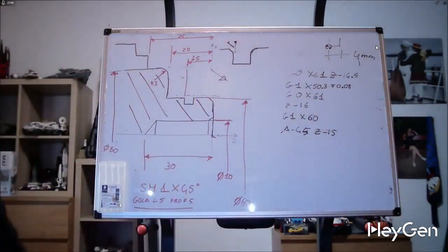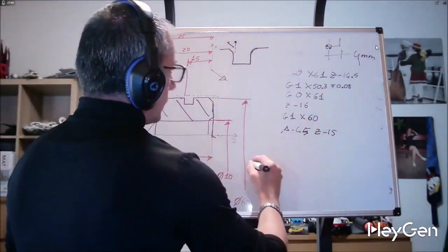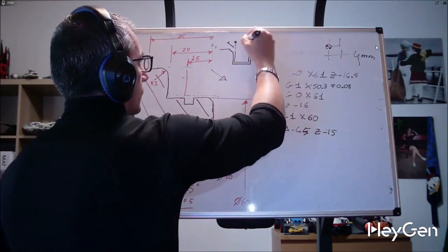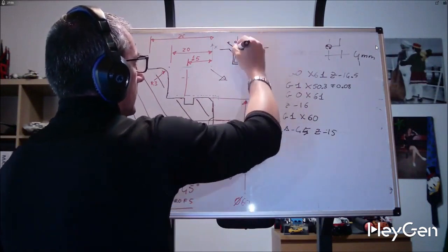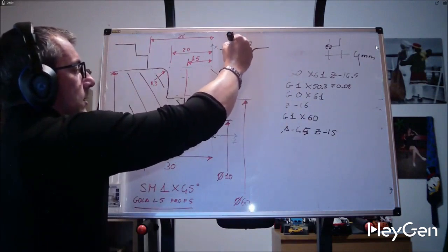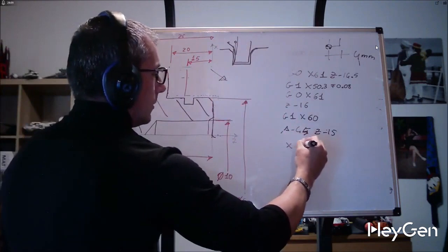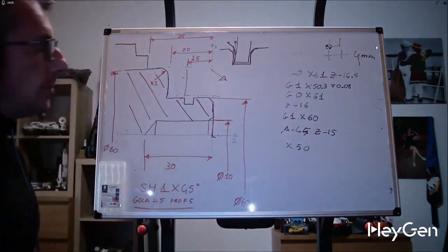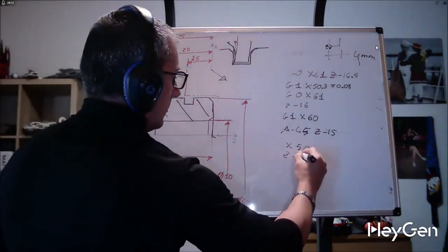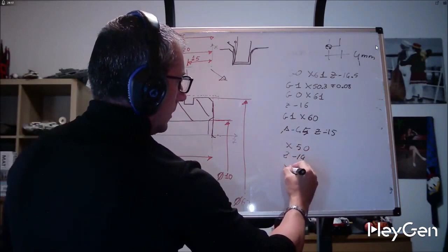How much do I move to make a groove 5 wide with a 4 tool already roughing the groove? Because we have already discussed this with the first plunge. I am here at 45, Z15. I go to the bottom. So G1, X50. Obviously, I will just need to widen by 1 millimeter. So Z14 and return to X60, 1, 14. And return to X.